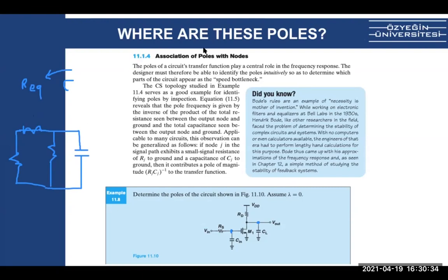So just like remember in the Thevenin theorem last year, we covered the circuit and we looked at the direct method, RT. What is the resistance? If there's a voltage source, you short the voltage source. If there's a current source, you open it. Then you look at the RT, direct method, and that is basically your R equivalent.